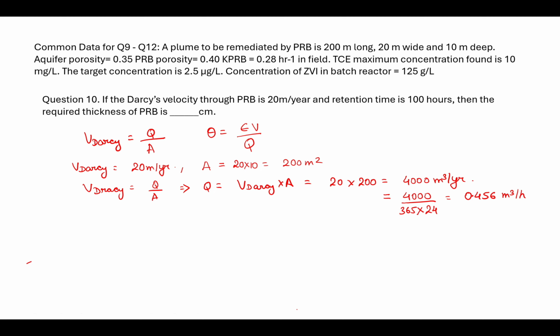So next, we have to find out the thickness. Retention time is given as porosity into volume of the PRB divided by discharge.